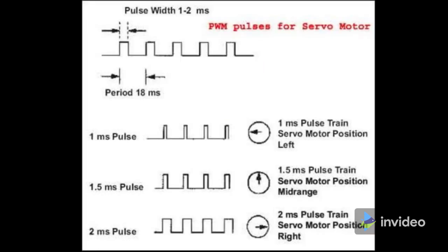When we press switch S1, the 555 generates a long duration high pulse, which high pulse time would be equal to 0.693 × (R1 + R2) × C1, and low pulse time would be 0.693 × R2 × C1. Thus, in this case, the servo moves in the right, that is clockwise direction.